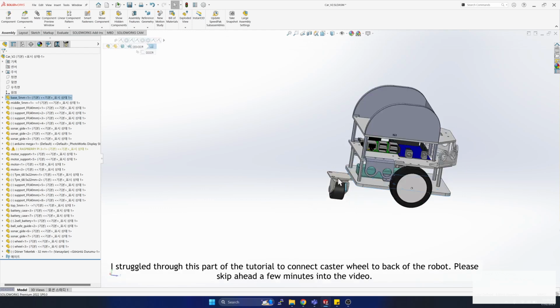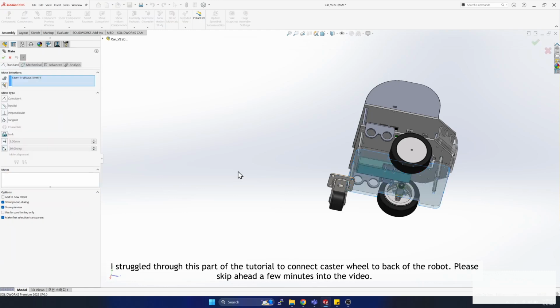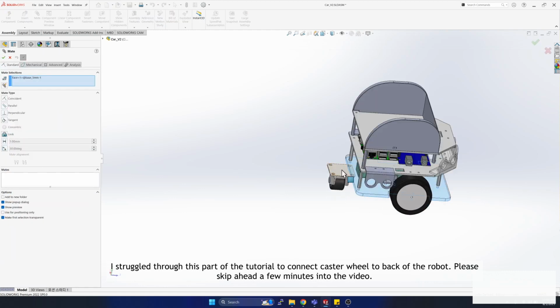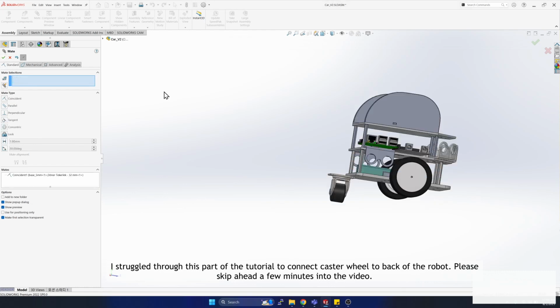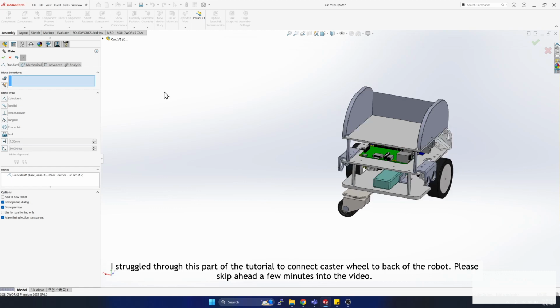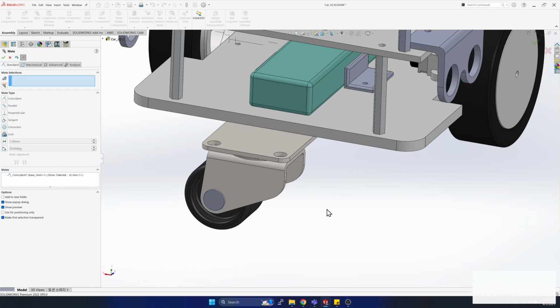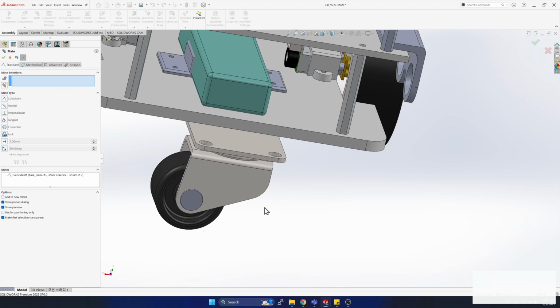this to this one. You can do that using mates in SolidWorks. I'll select this face, click on mate, and then select this face, and they should both be coincident, which means they'll be connected. That's one way. Because it's kind of like a fixed joint, I can now move it in the XY direction, or rather the faces will always be like that. I'm sorry, I think they should be parallel also, but let's focus on this in a minute.